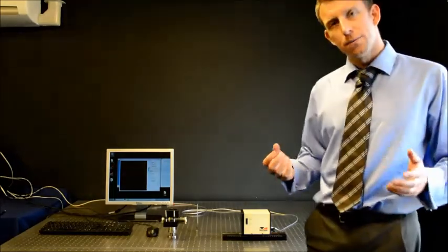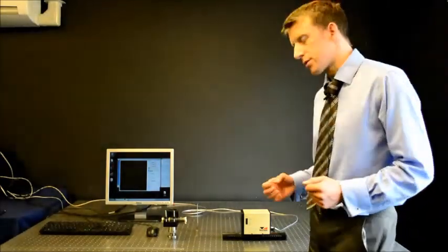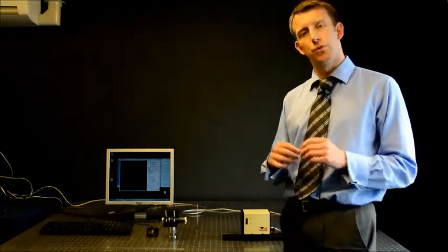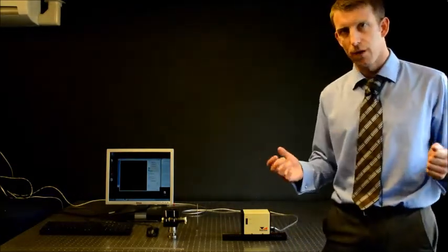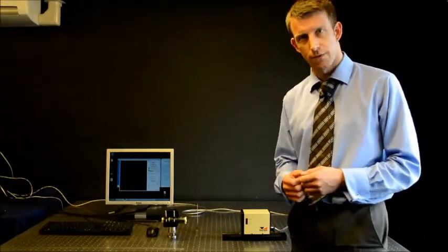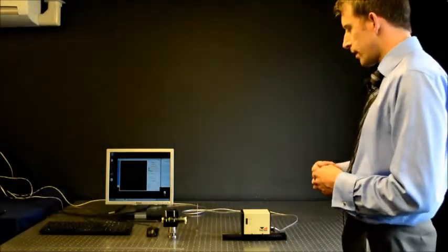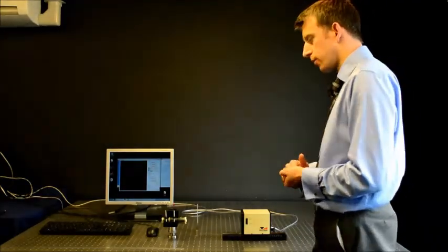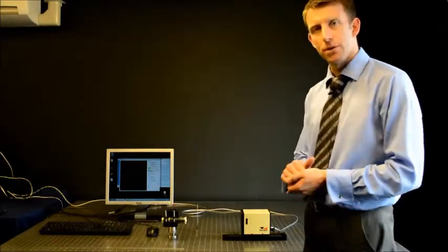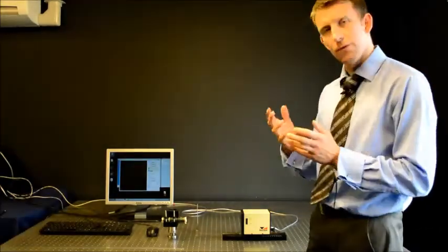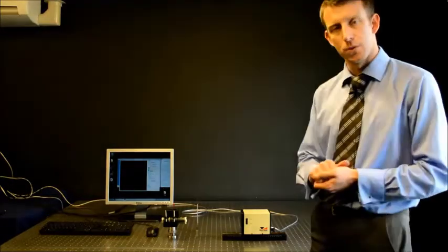Now, the PSL Profiler has been designed so that it has a good resolution over the 1.7 to 100 milliradians field of view, which are considered by IEC and EN 62471. Its minimum measurement distance intentionally was 200 millimeters, but can be used down to 100 millimeters where that is required. For this purposes here, we will use 200 millimeters.